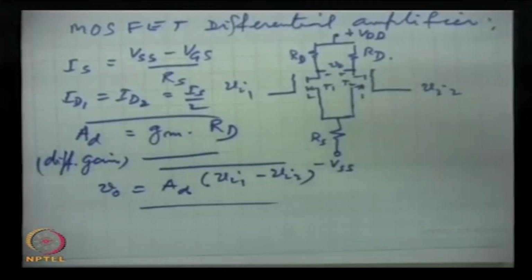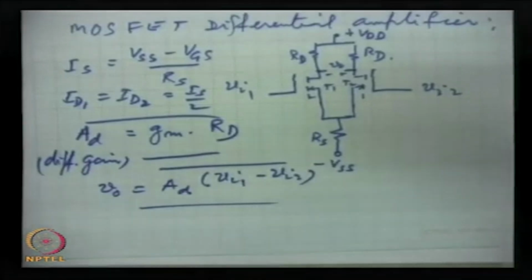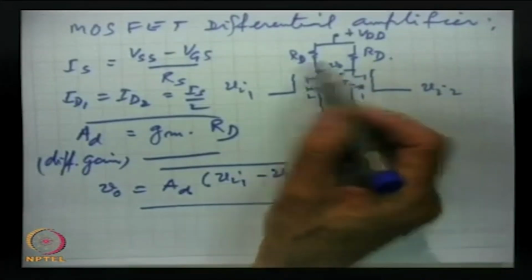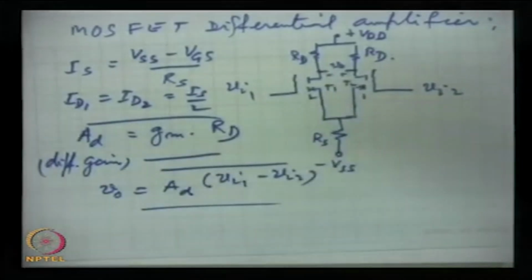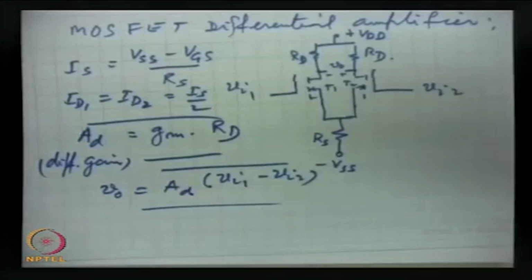Differential amplifiers are common with MOSFETs also. When very high input impedance, in megohms or rather still higher, is required, then MOSFETs are used, and this will be the requirement in several instrument fabrication. So, these differential amplifiers are used.